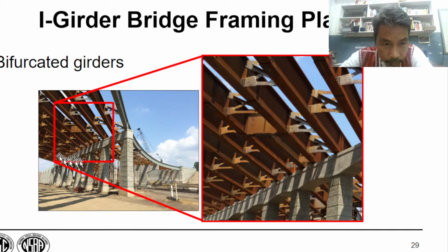So we have this specific area. So enlarge here. We have enlarged that section. What can we see? So there is no transfer beam here. No, there's no transfer beam. Oh, there is a transfer beam here. This is the transfer beam. This is the beam that supports the starting of a new girder. This is a new girder. This is the end point of the girder. Started here, which is being supported by this transfer beam.